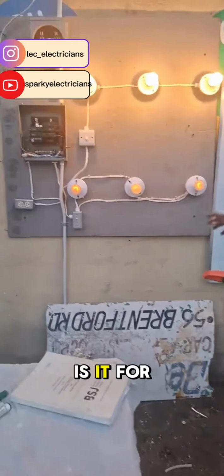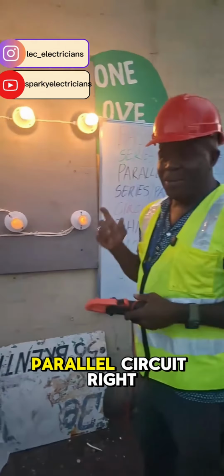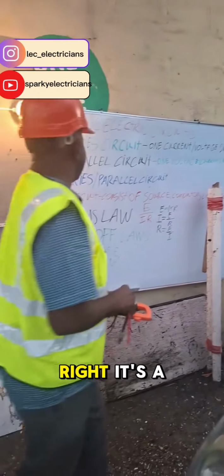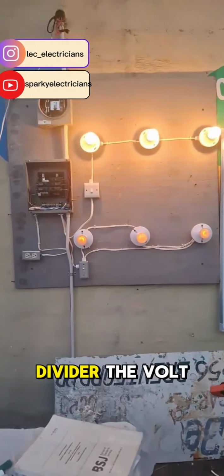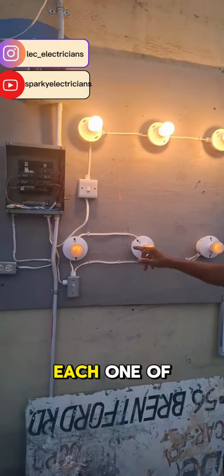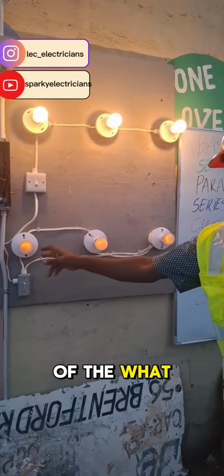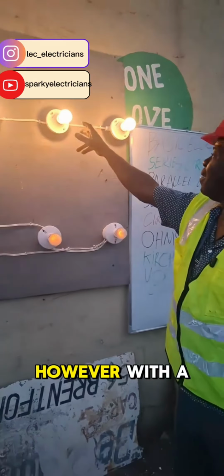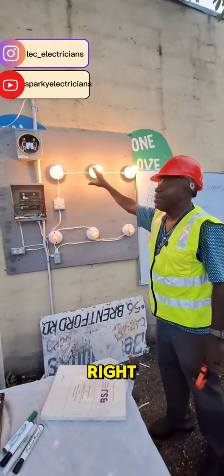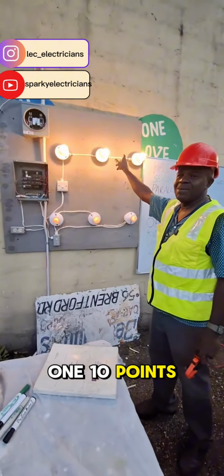So that is it for today. Series circuit and parallel circuit, right? A series circuit is a voltage divider, the voltage is shared. So right now, each one of these bulbs is getting a third of the voltage, right? However, where the parallel circuit is concerned, all three lamps, I should say, are getting the full 110 volts, right?